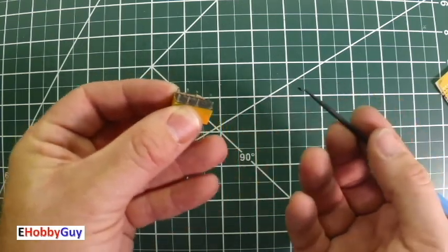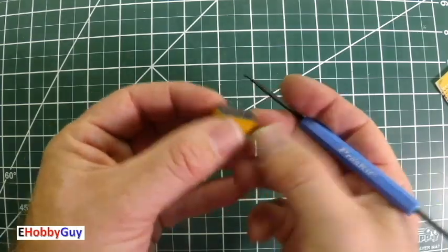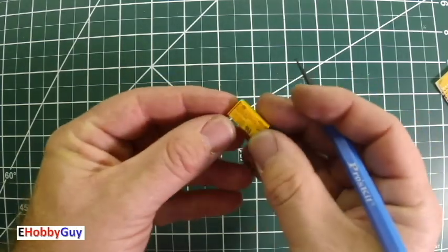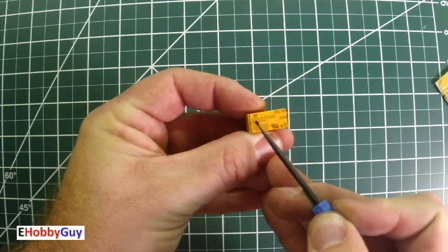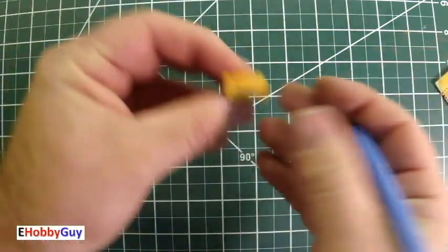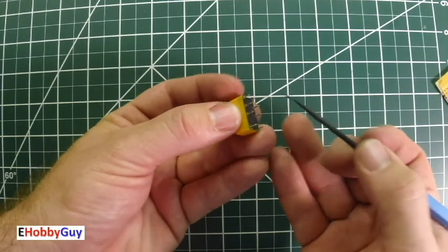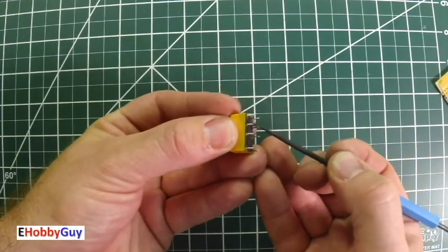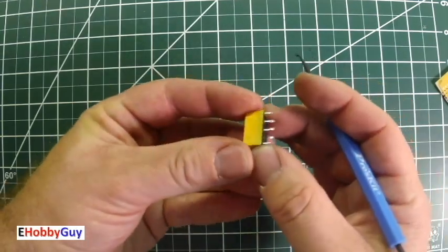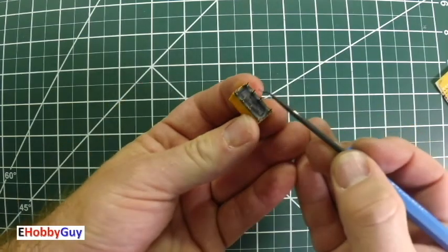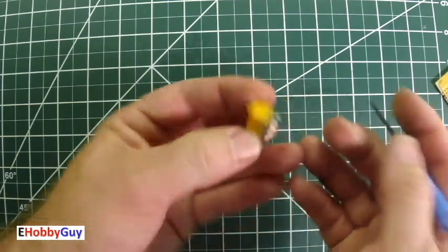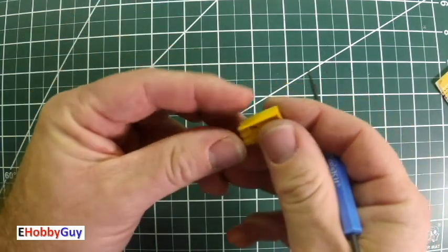And if you get a reading for the coil resistance, you'll know that it's the coil. But the first stop you should make when using a relay is to look at the model number and get the data sheet, as always, and it'll tell you which one's common, which one's normally open, and which one's normally closed. And so this looks like it's a Form C double pole double throw PCB mount relay.